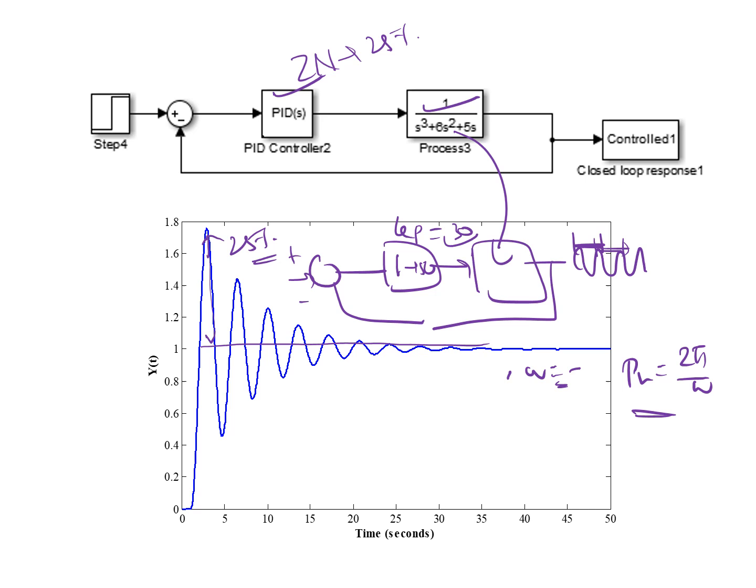Now it was in proportional control, then move to PID controller, substitute the parameters and make sure from this table you will get only the integral time. But in MATLAB, it will not take integral time, it will take only integral gain. So you have to take the reciprocal of this, which is equal to ki. Okay, you have to do this exercise. Don't forget to do that.